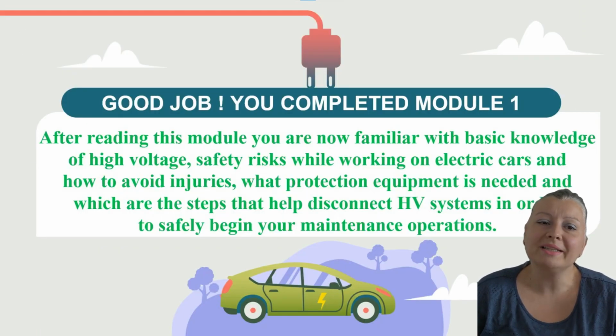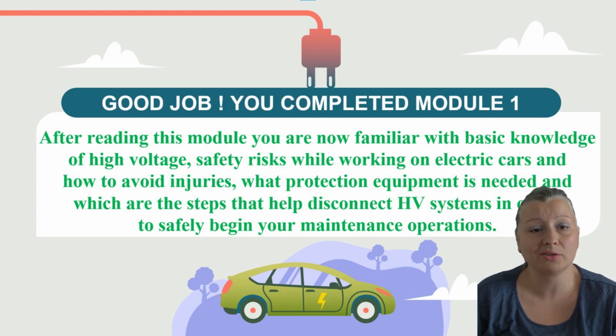Good job! You completed Module 1. After reading this module, you are now familiar with basic knowledge of high voltage, safety risks while working on electrical cars, and how to avoid injuries. What protection equipment is needed, and which are the steps to help disconnect HV system in order to safely begin